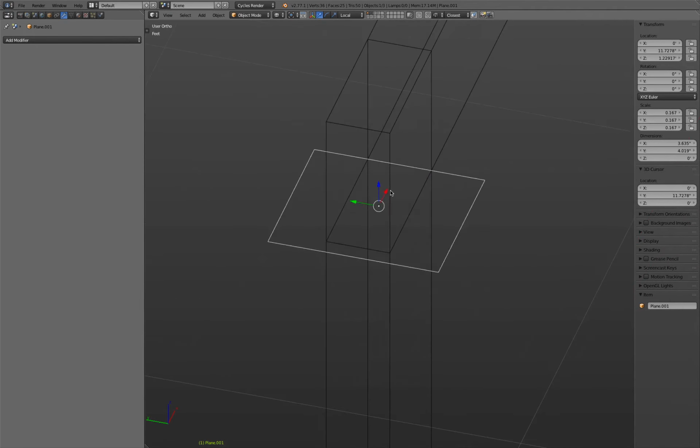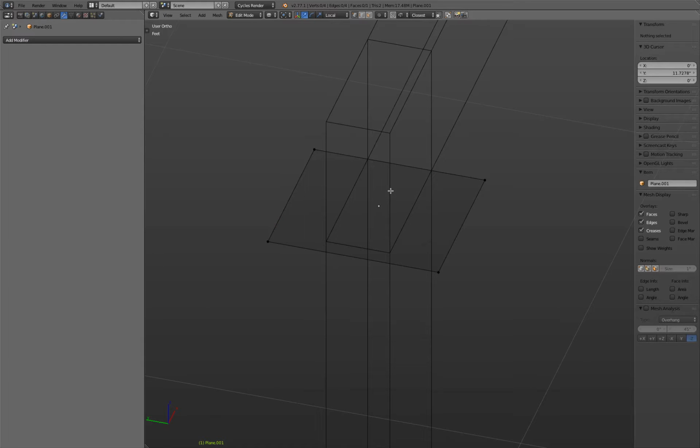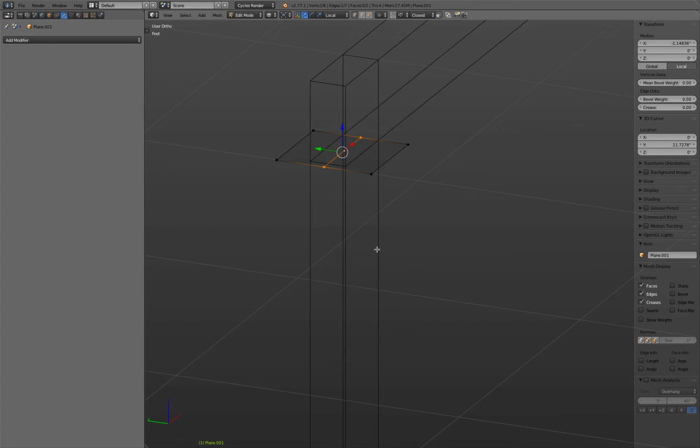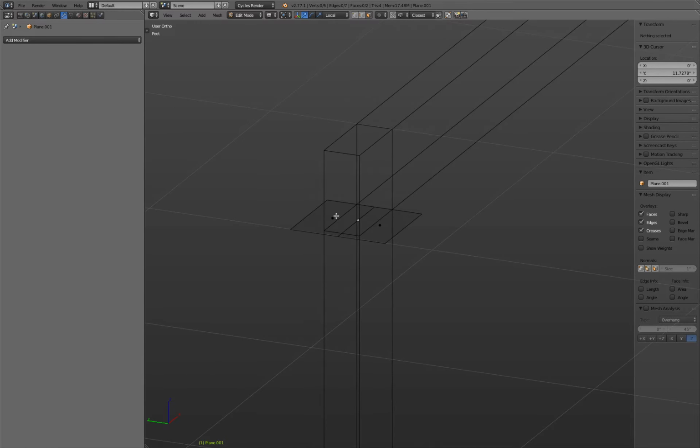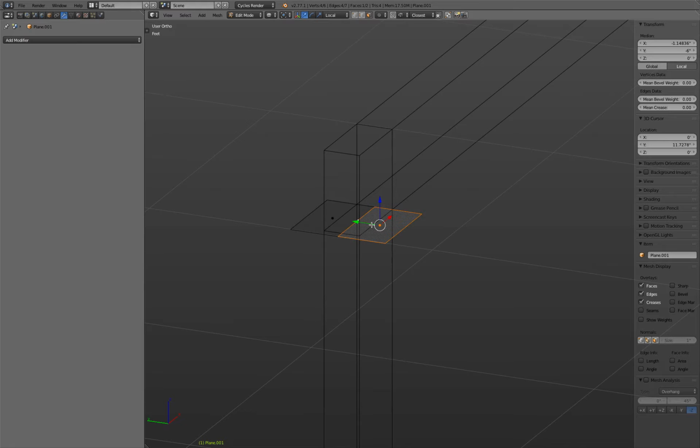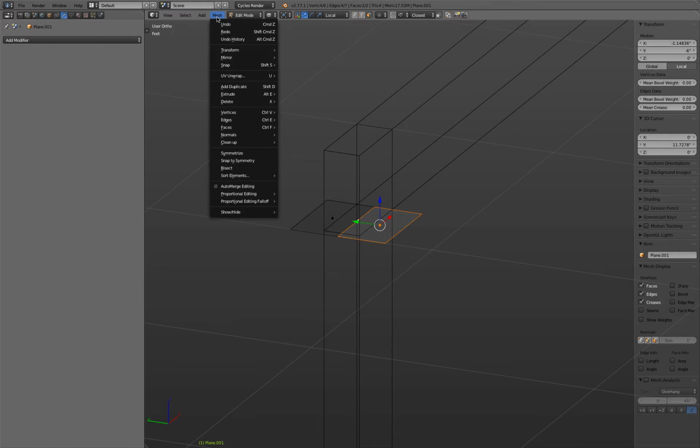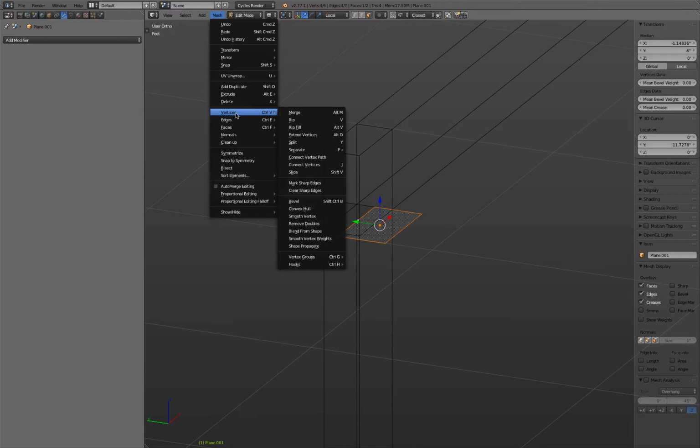Okay, so now we can go into edit mode, K, or there, click and control, click, press enter, and now we have this object. Perfect, two faces. But the problem is right now these two faces are in the same object. So what I will do now, I will separate this selected face out into a new object. And we can do this by pressing in edit mode P. And I think it is properly separate